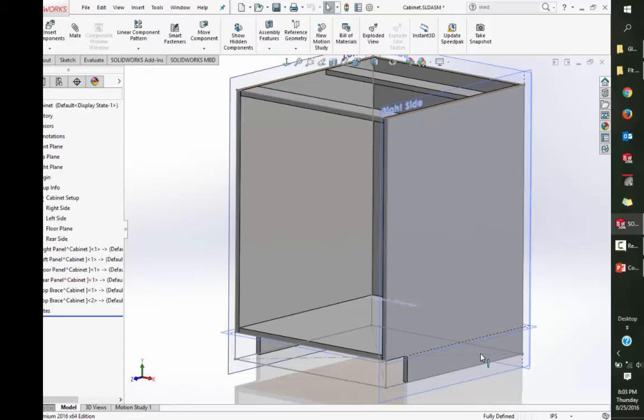All the parts have updated at this point. I'm all good to go. Now the thing is, I don't want to have to get into the sketch, double click and show it and not show it and all that good stuff. So what I'm going to do is use those global variables. I'm going to connect everything up to a global variable, and then go the next step farther and say I'm making a configuration part. Not making configurations, I'm going to make a configuration part.